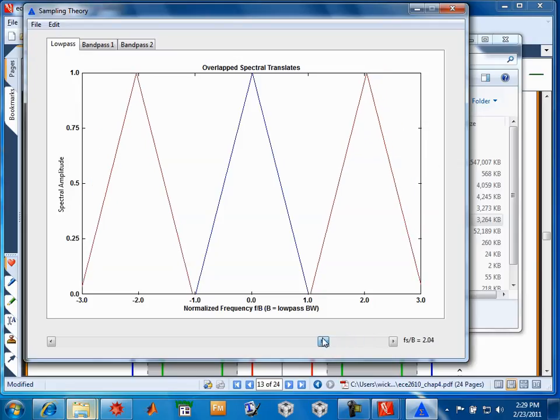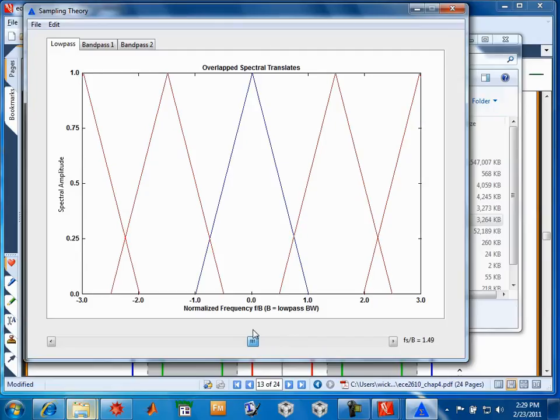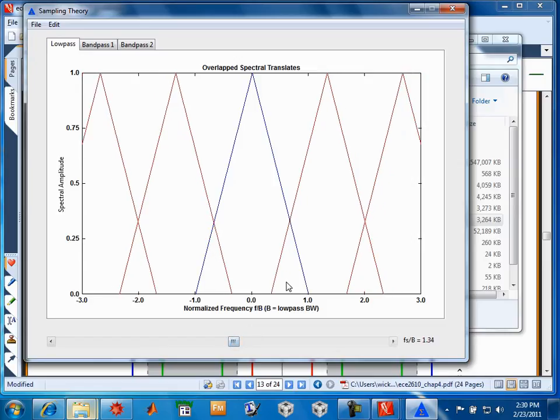But if I don't sample fast enough, then here's what happens. You start getting this overlap, and that's another way of depicting aliasing. If I was not sampling at a high enough rate, what would happen is if I tried to reconstruct this signal, we would get back portions of the blue, but where the blue overlaps right in here, it folds around, and now I'd hear, instead of the spectrum that would go up higher in frequency, suppose that was part of my speech, it would instead get mirrored about that crossover point, and I'd hear all those frequencies actually out of the lower aliased frequency. And that is going to sound like what? Exactly. It sounds bad. Is that believable?